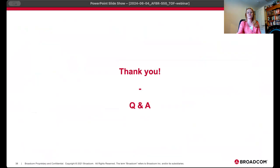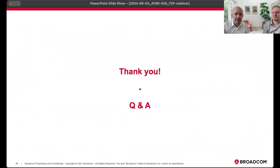Yeah, actually the reasons, first of all, is also availability of light sources. When you look at the market, there are some specific light sources where you have the freedom to select your suppliers. So this is one reason. Another reason specifically for the 680 nanometer is that we wanted to have a sensor where the sensor spot is visible. We have a couple of sensor customers who require to see the spots where we are measuring the distance. This gives you a visual feedback by the eye where the distance is being measured.